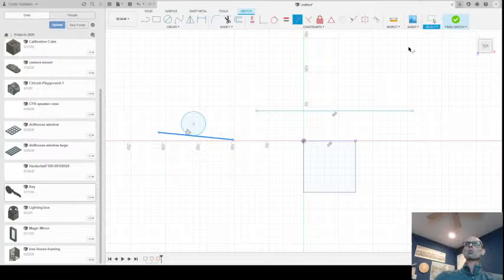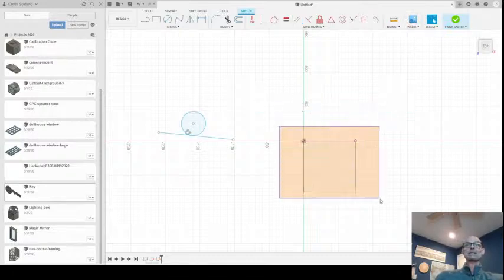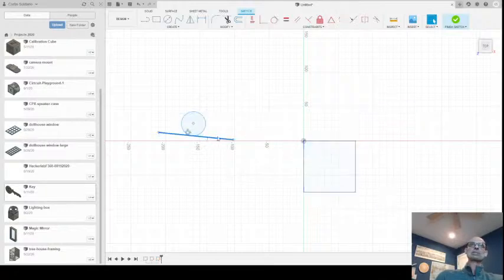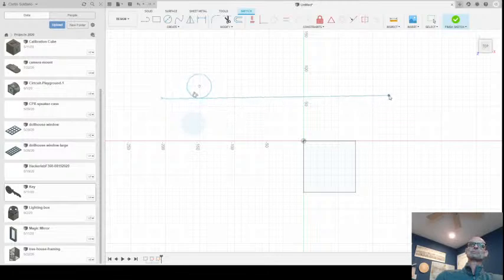I'm going to walk through just the logical thought process, and I'm not even saying that my thought process is a good one, but I started thinking about how would you use this in real life. So here we have the line tangential to the circle. I can still keep the angle and so forth, but you know what? I'm going to get as close as I can, but I'm a little off today, so I didn't get it quite right. So then let me add a constraint to that. We're going to add the horizontal vertical constraint.